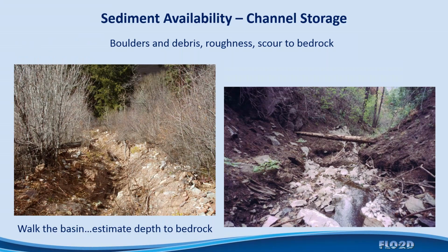So walk the channel, estimate the depth of bedrock, take some pictures, and get an idea of how many reaches you might have where there is some storage of material. I call it having the channel charged with sediment and boulders and maybe some debris, logs, and so forth. Try to get an idea, as you walk up the channel, of how much of the channel or how deep the channel might scour in order to reach bedrock. You can make a pretty good guess at this. Sometimes I take a hiking pole or a rod and try to spike down a little bit through the material, but that's kind of hard to do.